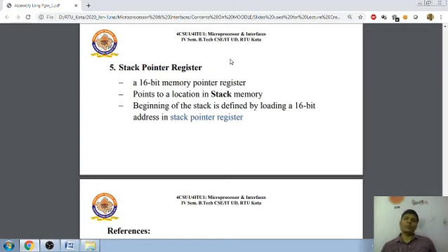One stack pointer is enough for a stack, because a stack works on only one location at a time. The stack pointer will be at the top, then you will be getting down in reverse order of your subroutine calls, because a stack is a first in last out approach. The last call of your subroutine will be executed first, and the stack pointer is the one which gets updated after each call of your subroutine.